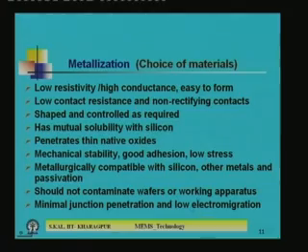If you apply an electric field, then the metal molecules or atoms should not migrate. In VLSI metallization, even if you use, say, a 1.2 volt supply or 5 volt supply, if the lines are very narrow, the field developed from one end of the metal line to the other will be very high. If it exceeds 10 to the power 6 volt per centimeter, then there is a possibility of migration of the molecules.